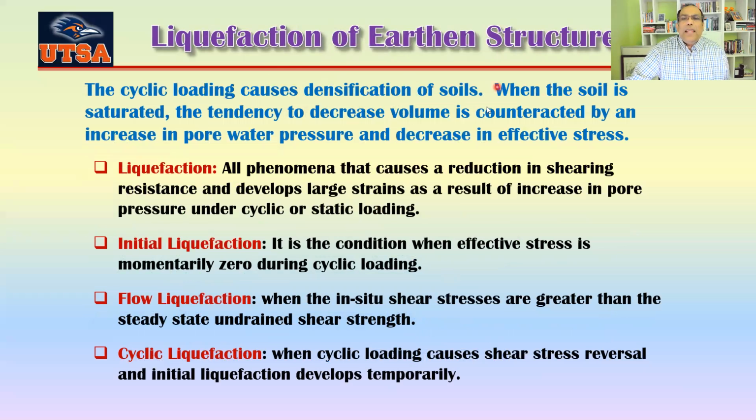Now, what happens for earthen structures, most importantly, is liquefaction, which can happen to any earthen structure. The cyclic loading causes densification of soil. When the soil is saturated, the tendency to decrease volume is counteracted by the increase in pore water pressure and decrease in effective stress.